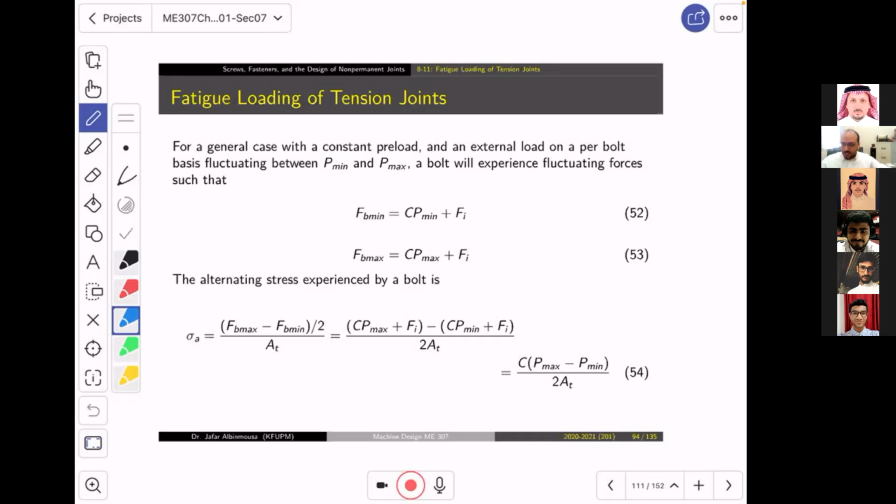So in general, whatever is in fatigue is the fact that there is a possibility of having a mean load, which is the red line in here, and a possibility of a fluctuating load, which is the amplitude. The amplitude, guys, is what goes up and down. The steady one is the mean. That's why we call it amplitude and steady loading, or mean. All right. Now, we all know that the analysis of any cyclic loading can be easily established by giving me the maximum and the minimum.